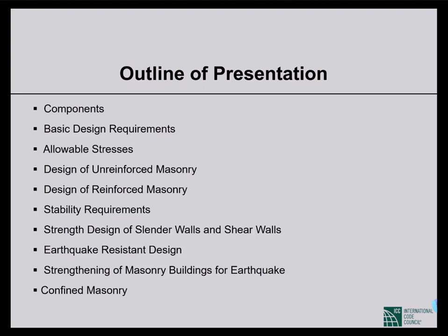On the other side of the brick, we also take out a brick. So we have an opening on the other side. When you put pressure on one side of the brick, the stress comes to the joints. And when it fails in shear, then we can understand the in situ shear strength of the brickwork.